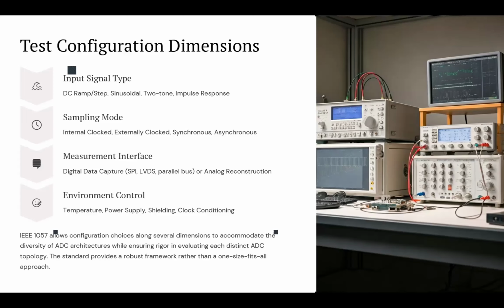result. For example, if the temperature changes plus or minus 1 to 2 degrees Celsius, it would introduce an offset drift. Okay, because it changes the characteristics of the circuit. Or a noisy power supply introduces inaccuracy or extra distortion in the output, making the ADC deviate more from a linear performance to a more distorted nonlinear performance.